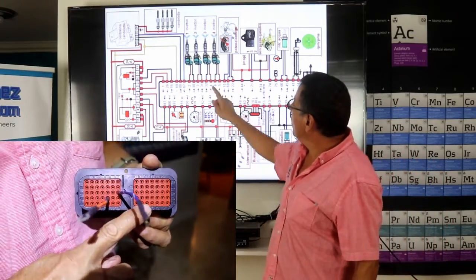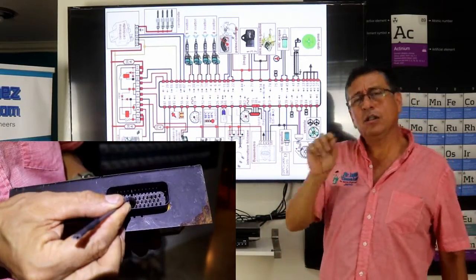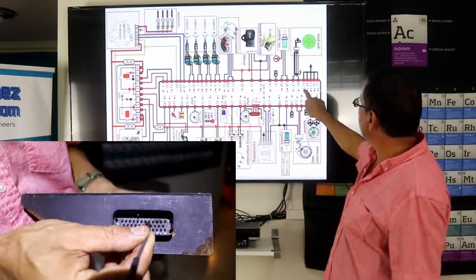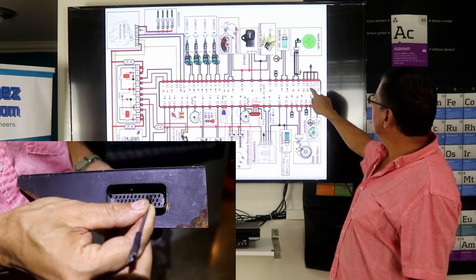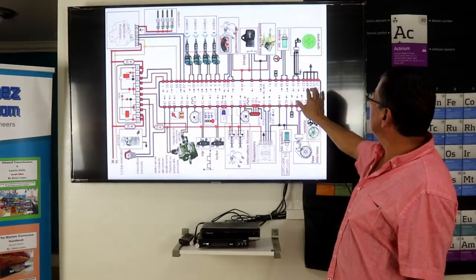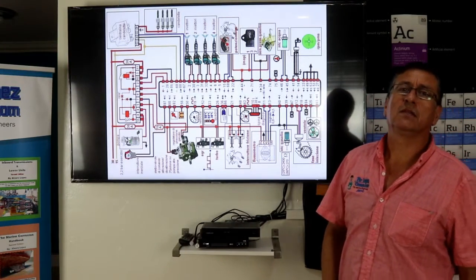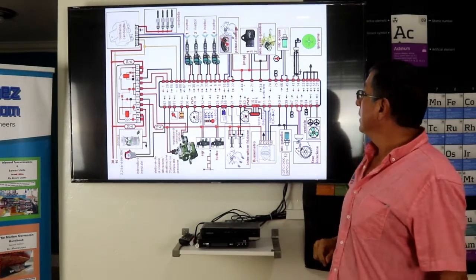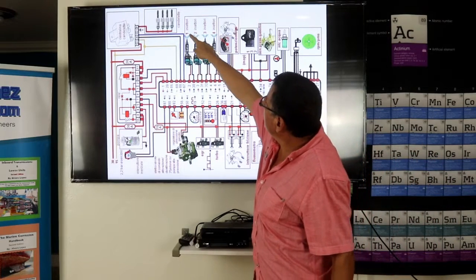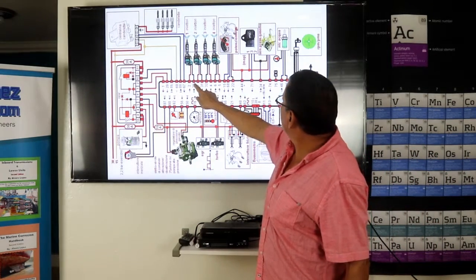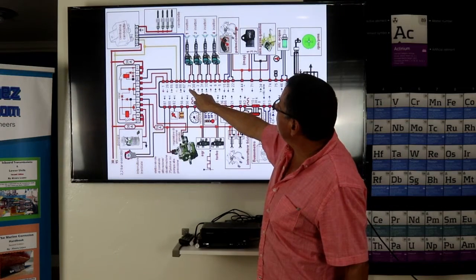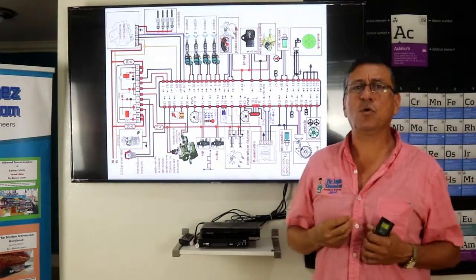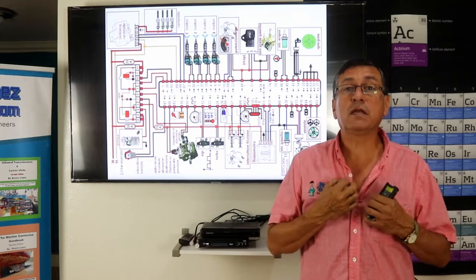Oh, the injectors. One pin is negative. Normally, all the sockets have one group of pins dedicated for ground. Look at this: pins 33, 49, 53, 51, 27. Those are negative pins, connected to the negative of the battery, the negative DC bus bar. For example, for injector number one, one pin is connected with ground, and the other pin, pin number 2, is the power for the injector. Oh, I have a problem in injector number 2 of my engine. Let me check with my multimeter carefully.